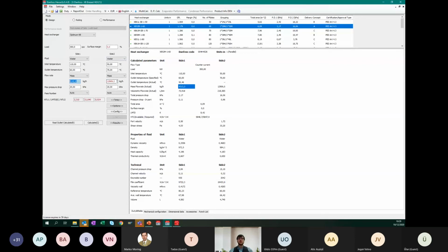If you have an asymmetric flow rate, with a much higher flow rate on the secondary side, as I said, your heat exchanger selection will be limited by a hydraulic factor on the secondary side, by the pressure drop on the secondary side. And in most cases, when we are designing a system, the most critical pressure drop for us is actually the primary pressure drop, because this is a pressure drop from a district heating network where we should be quite strict on what we have.